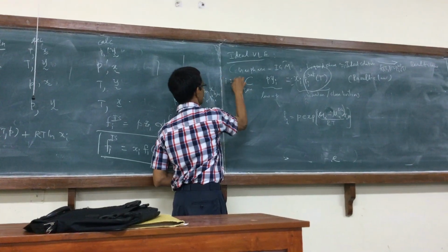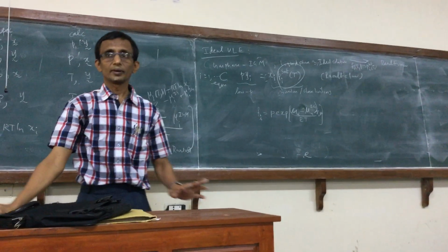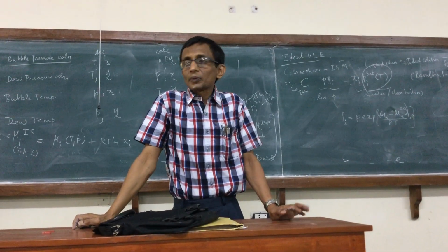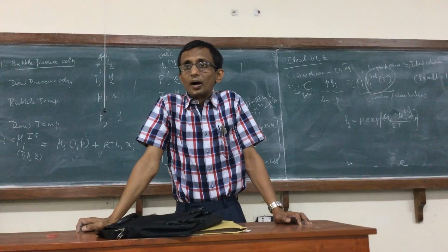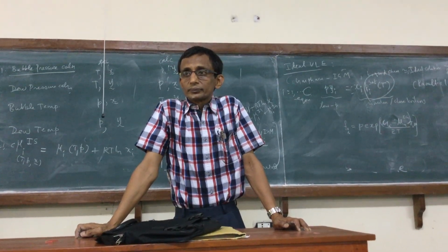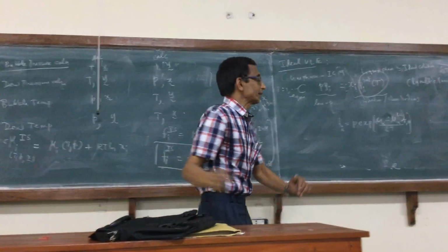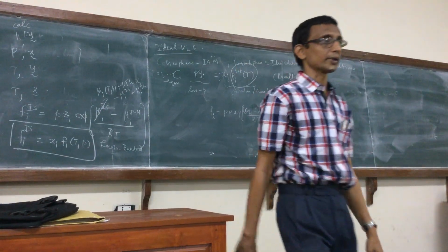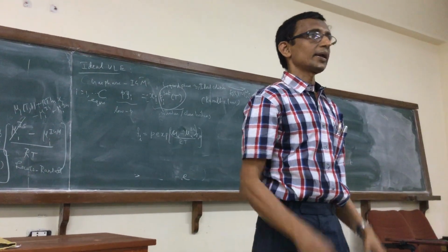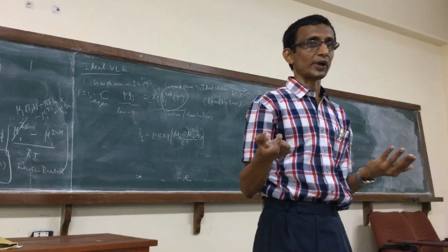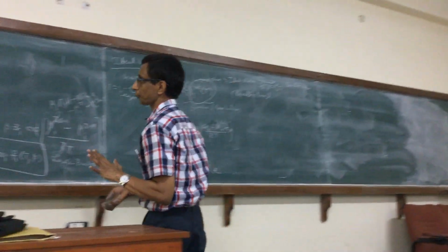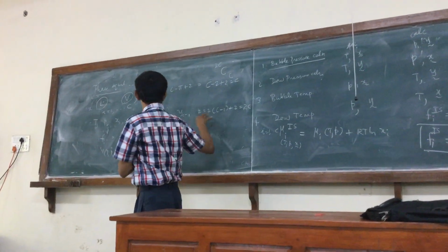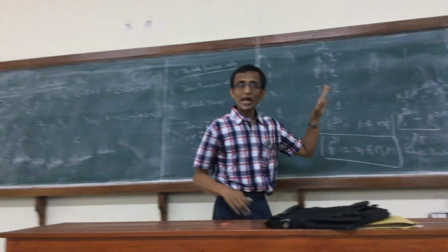Right? Because i equals 1 to C, C equations are there. But however, how many variables are there apart from temperature and pressure? C variables are there, because by writing it as i equals 1 to C, if I want to write it uniformly for all components, then I have to explicitly bring in all the C mole fractions. So there's a subtle difference between what we consider when we specify variables and arrive at all this, and when we actually do the calculation.